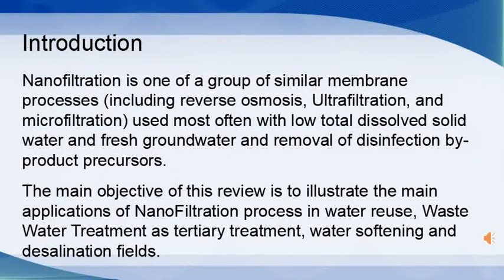Nanofiltration is one of a group of similar membrane processes that include reverse osmosis, ultrafiltration, and microfiltration. It is used most often with low total dissolved solids water and fresh groundwater, and for removal of disinfection by-product precursors. For example, we can see this system used in landfill.